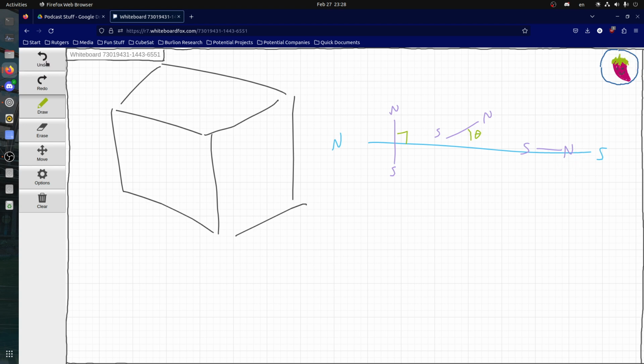So as you're spinning, the magnet torque will slowly decay your angular velocity until it's slow enough that your reaction wheels can take over. The reason it's called detumble is because you're spinning uncontrollably. So you turn on your magnet torquers and let them slowly bring down your angular velocity until your reaction wheels are able to control it and compensate for the errors.